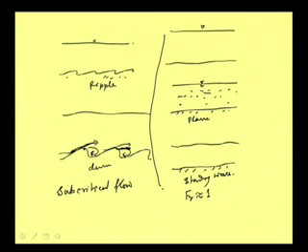Then after this situation, the flow will be in another stage that is called anti-dune. It will be a very big size dune, and it is symmetrical. This was leaning in the forward direction, but this will be symmetrical like this, and of larger size. And those sediments are moving, and here the surface can also break like that. The surface can also have some discontinuity in it.